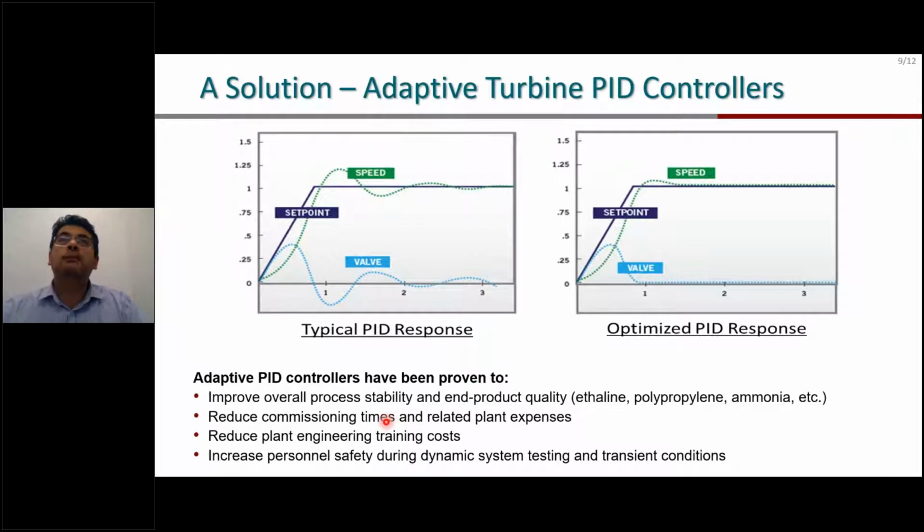We also reduced the commissioning time. Before, an engineer would sit down with the operators and tune a value and wait for the system to be stable, then put in another value and wait for the system to be stable. By using OptiTune or adaptive PID tuning, we have consolidated all these experiences, and we use less time for commissioning of the turbine. And there is the convenience of just pressing a button within your controller itself, whenever you see any disturbance.